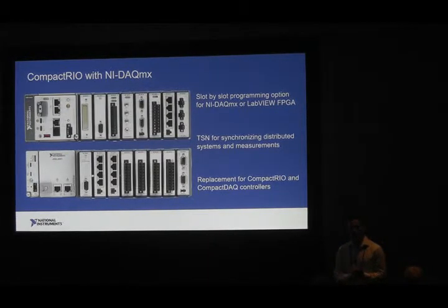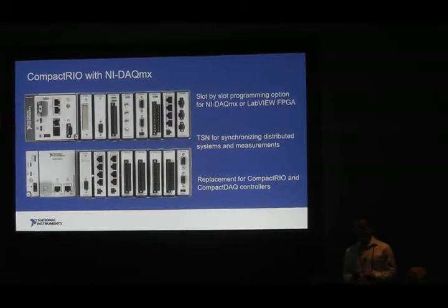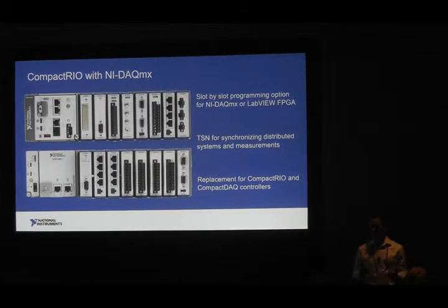One is now you have the ability to choose on a slot-by-slot basis which programming mode you would like to choose. So for each individual slot, you can choose between DAQmx, you can choose between LabVIEW FPGA, or, I'll briefly mention now, you can choose scan engine, so the RSI, as well as an option.